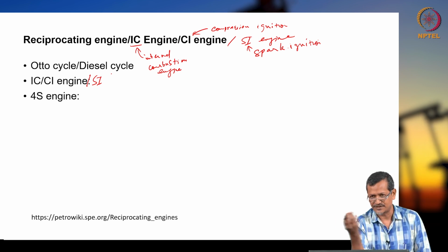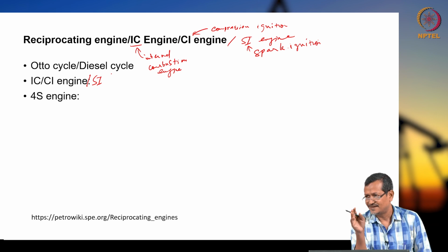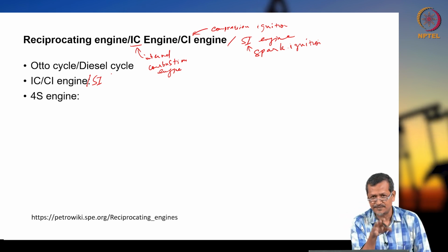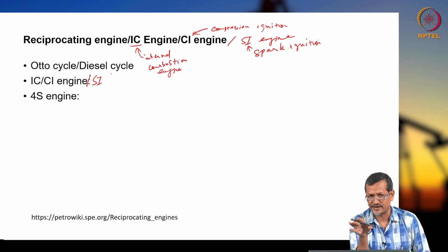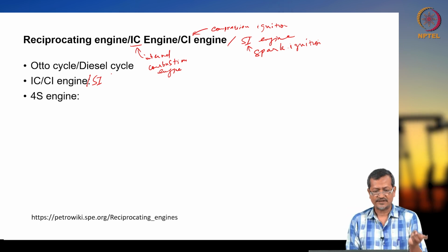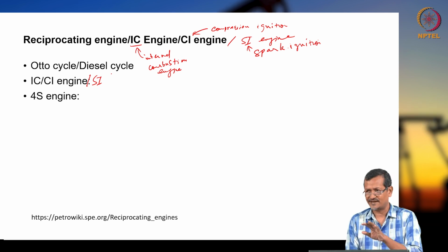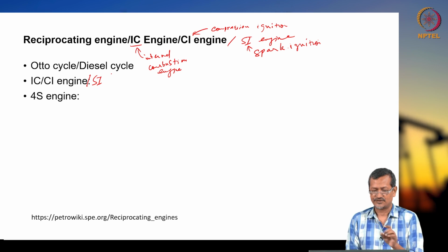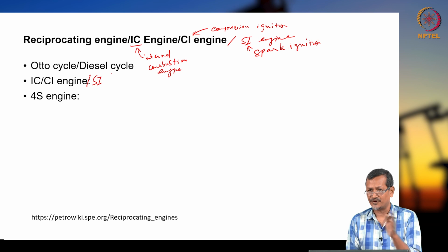That's why white smoke or hydrocarbon vapor comes out. Hydrocarbon vapor coming out means all the fuel is not burned. That means the fuel did not get proper oxygen. That means some carbon will become carbon monoxide also. Carbon dioxide is not harmful actually. Although it's a greenhouse gas and other things, all the engine designers will try to produce carbon dioxide. So carbon dioxide will not give you a problem. Carbon monoxide has a severe problem. So our target will be to produce carbon dioxide, not carbon monoxide.